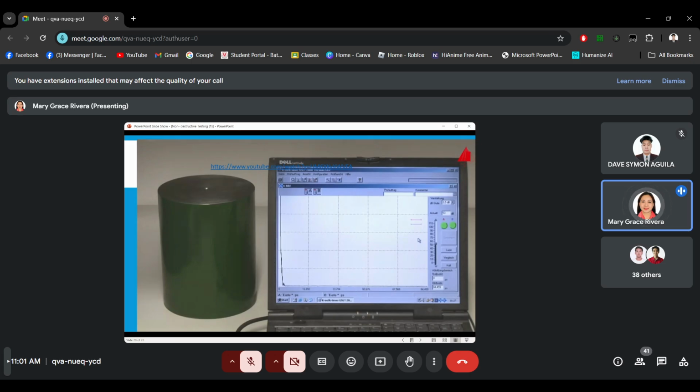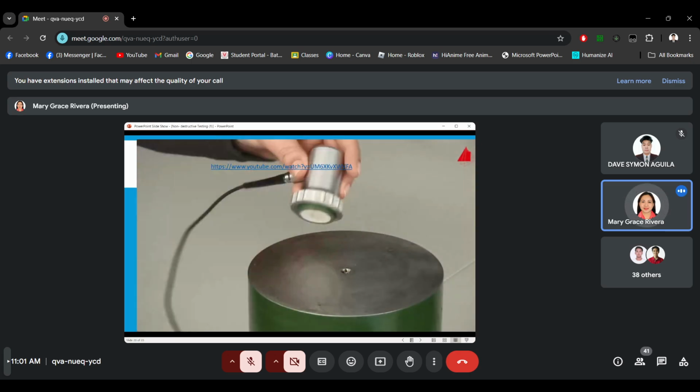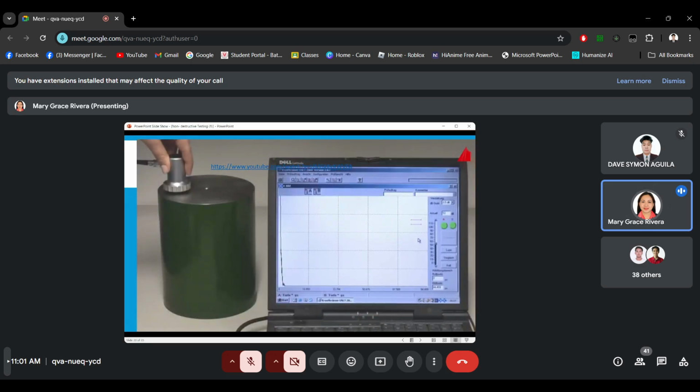After placing the probe on top of the cylinder, initially no echo at all may be seen on the monitor. The reason for this is the too small contact area between the probe and the workpiece. Only with the use of a gel, the so-called couplant, the ultrasonic pulses can get into the workpiece and can also go back to the probe. Now the back wall echo turns up on the monitor. The material tester spreads out the gel evenly on the top surface. That way she is able to examine the entire cylinder.